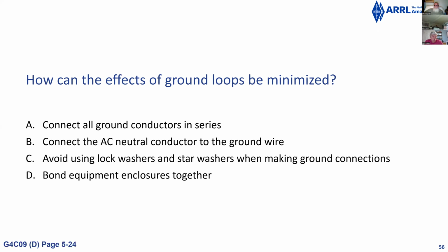Another way to look at bonding is that you want a very firm ground connection that covers a fair amount of area. And that's important. Area of the ground connection means that the resistance through that interface between the chassis and the ground wire or cable is going to be lower. And so it will be an easier path for RF to drain away, or unwanted voltage difference.